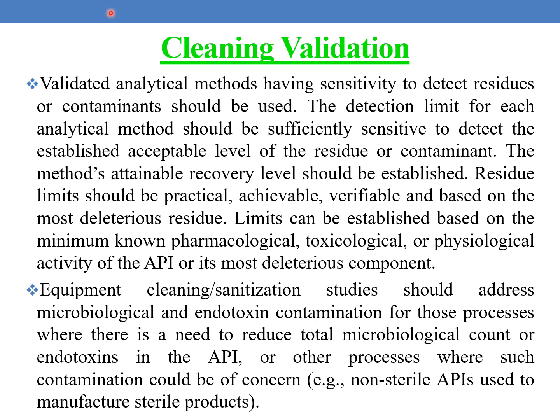For cleaning procedure validation, a validated analytical method having sensitivity to detect the residues or contaminants should be used. The detection limit for each analytical method should be sufficiently sensitive to detect the established acceptable level of residue or contaminant, and the method's attainable recovery level should be established.